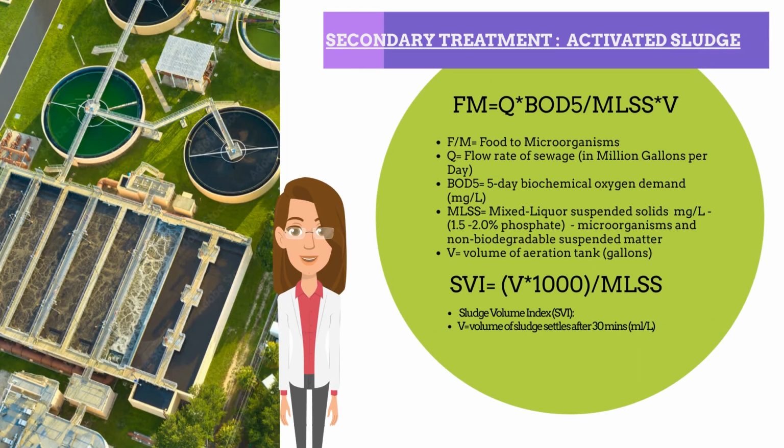Recycling the activated sludge biomass allows for larger quantities of microorganisms to oxidize organic matter quickly. As mentioned before, this activated sludge slurry goes back and forth between the aeration tank and settling tank. The content of the aeration tank is known as the mixed liquor suspended solids, MLSS. The organics in the MLSS are called mixed liquor volatile suspended solids, MLVSS. The MLVSS is made up of non-microbial matter and dead and living microorganisms.